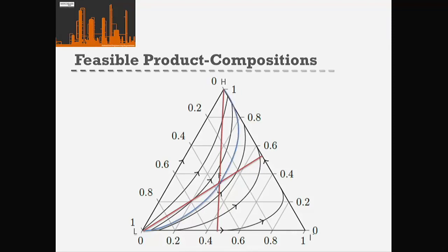What we also want to think about is actually the residue curve that passes through our feed point. Okay? So that's the residue curve that our feed point lies on. Now, if we think about this, and we think about where we can draw our possible lines that still satisfy lying on the same residue curve, but also passing through the feed, what we get is these two regions.